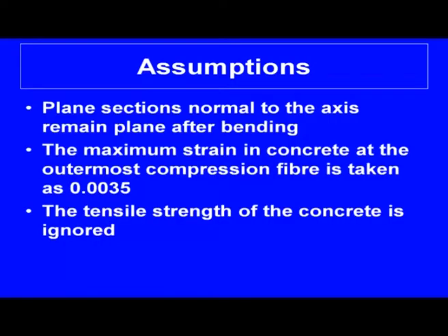Now in that, for shear also there is one for the column. Here what is taken by the concrete? Now how do I find out whether it is 20 to 40%, 15 to 25%? There is no such concrete value to find out. So we find the shear taken by concrete, which is nothing but VC, equal to aggregate interlock, dowel action, and other things. What we do is, on the basis of the percentage of steel we calculate it; in IS 456 it is given in Table 19. So the total shear portion will be taken by the concrete, and the additional portion we have to provide.